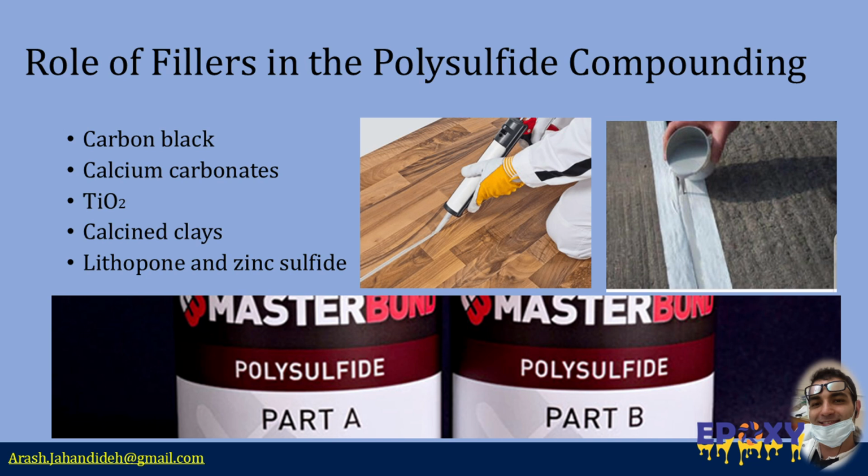Lastly, lithopone and zinc sulfide have been explored as alternatives to titanium dioxide. These fillers can provide similar pigmentation properties in applications where brightness or whiteness is desired but may be selected based on cost, availability, or formulation compatibility. Fillers not only adjust color and consistency, but also significantly influence mechanical properties, processability, and durability of the final sealant.